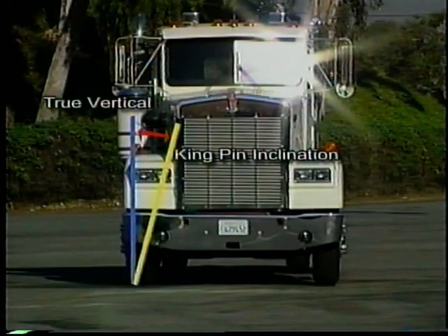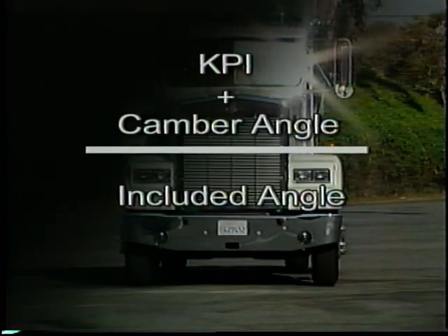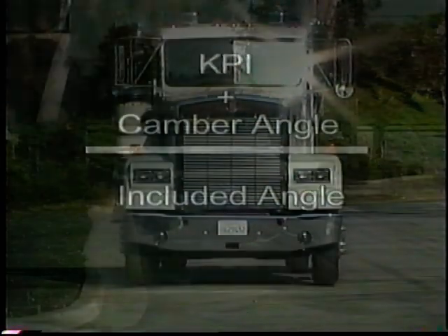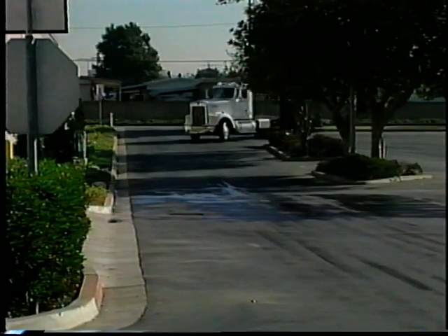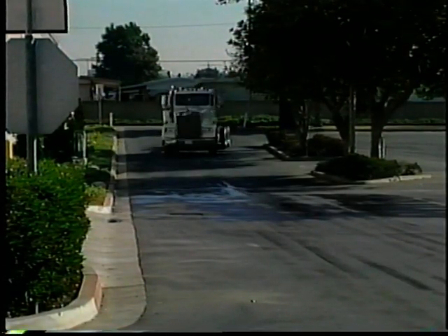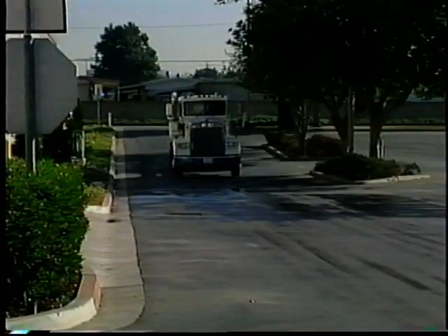Kingpin inclination, or KPI, is the theoretical line through the center of the kingpins in relation to true vertical when viewed from the front. The included angle is the sum of the KPI angle and the camber angle. KPI helps to return the wheels to a straight-ahead position after a turn. The higher the KPI, the higher the steering effort.